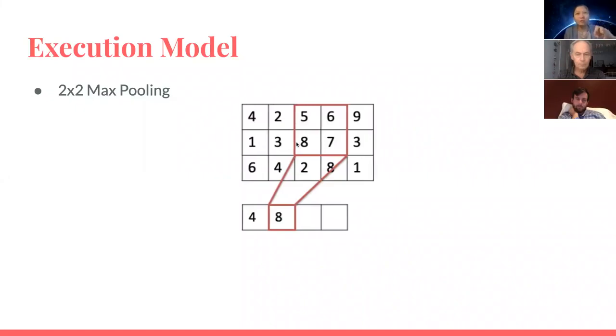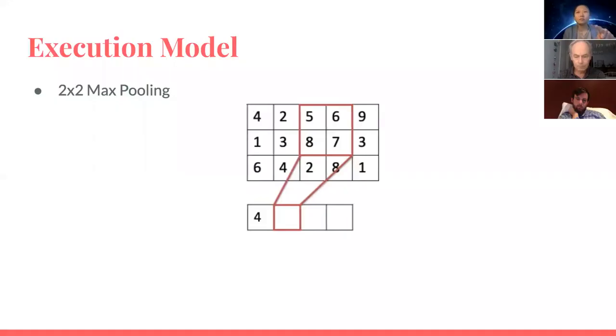Sorry, this is a little bit messy. In this case, we're assuming this pooling layer has a stride of 2. But sometimes if it's stride by 1, then this line buffer design will help us to reuse the input that we already loaded on chip. That's the whole idea.